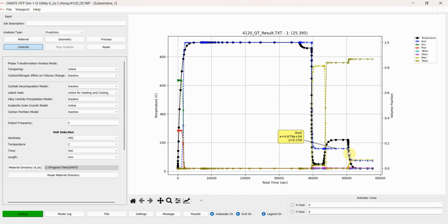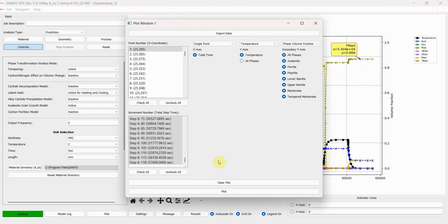When we cool down from tempering, it goes through the MS temperature again, and this austenite begins to decompose down to about 6% as-quenched martensite, another 6% there, and then there's a little bit of tempered martensite that's left over from the cool down as well. It gets to about 86% tempered martensite phase during the process.